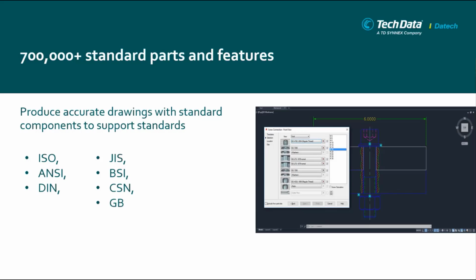You can add the current drawing to a custom library, or select geometry as custom content inside your library, and also add blocks that you repeatedly use in the form of DWG files, or even solid blocks, which can also be utilized as a library.